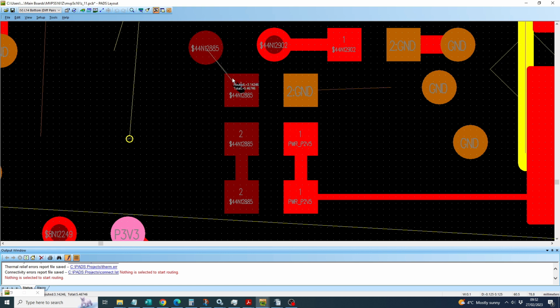So we can either, let's change the track width to 0.3. We can either double click and it will finish the route for us. Often that doesn't give a correct result or the desired result. If we do F2, you can see it's only changing in diagonal, so that doesn't quite match the via.